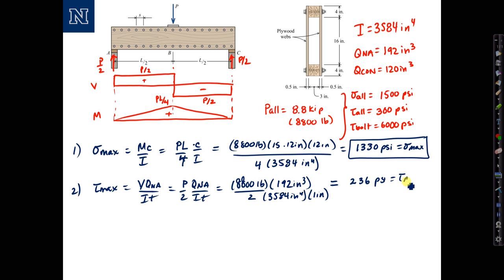That's the maximum shear. It's less than the allowable shear of 300 psi because this did not control the design.